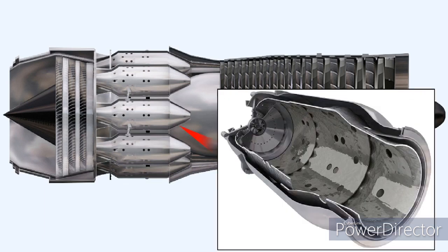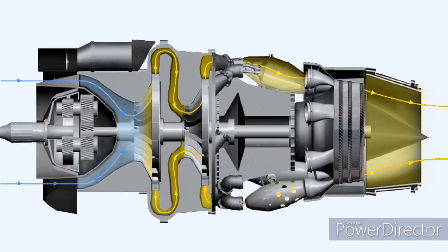Any remaining traces of fuel within the engine must be evaporated. To this end, the engine must be motored over on what is termed a blowout cycle. During a blowout cycle, the engine is turned over by using the starter motor. It's rotated for the time normally allocated to a full start cycle, but with the high-pressure fuel cock shut and the ignition system deselected. Air from the compressor will flow through the combustion chambers, the turbine, and the exhaust system, and assist in the evaporation of any fuel still remaining within.